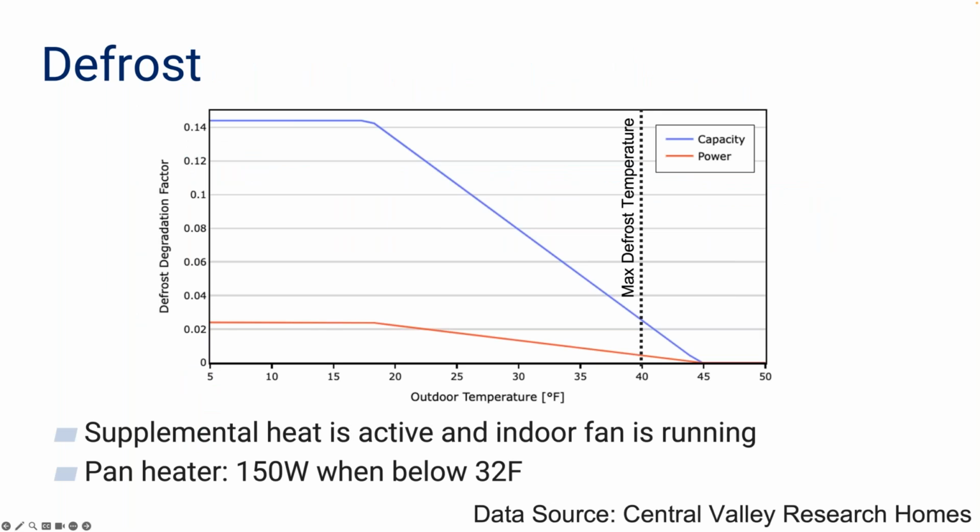Defrost is another big topic and another area where we have very little data available from the manufacturers about how the heat pumps work in defrost operation. And there's also a wide range of strategies that people can use to defrost the outdoor coil. But with whatever strategies they're using, it's not always documented in a way that can be readily determined by a rater.